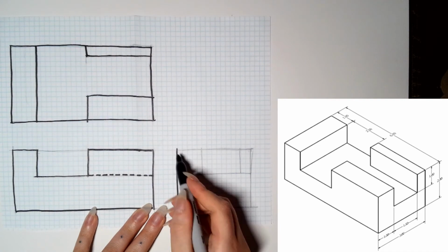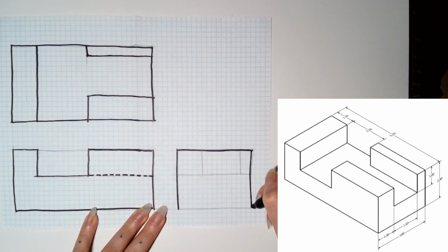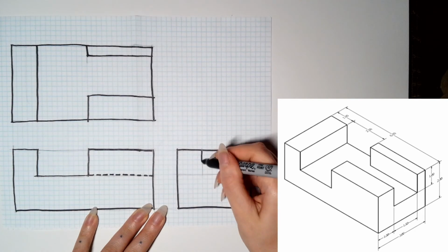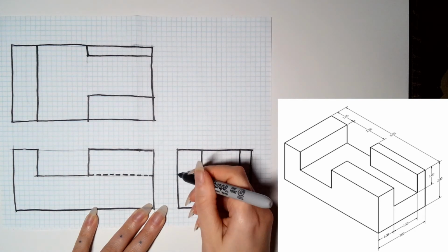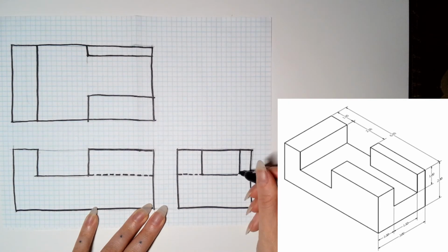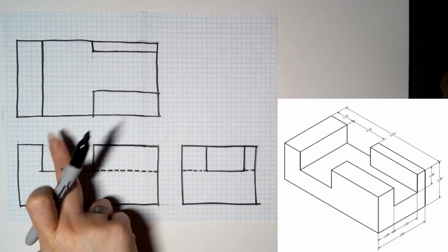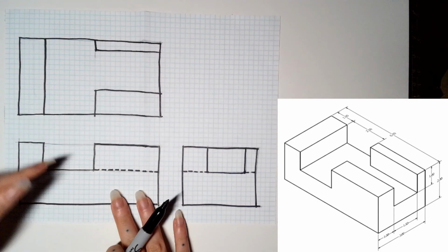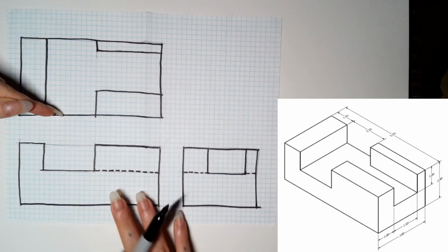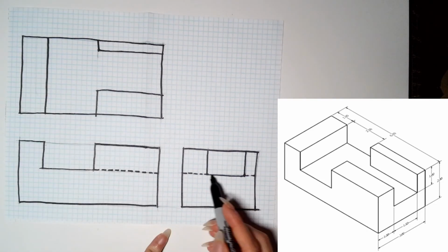Now in my side view, we have a hidden line going through right here, and then a small one also happening over here, because that line is defining this slot going all the way through up here. Excuse me, my arm was just entirely in the way. Going all the way through up here, but when I'm looking at it in the side, I can't see it. I can only see just that portion of it.